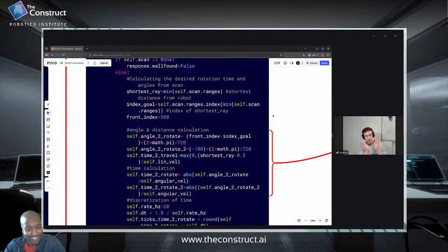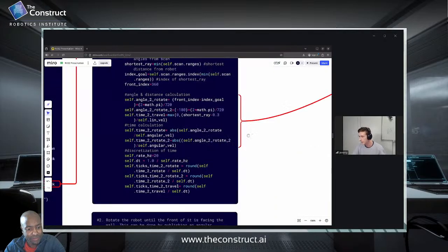I know the angle. The command velocity topic doesn't allow me to define a proper angle. So I had to define a timer for the rover to spin the distance. Since I got the angular velocity, dividing the angle by the angular velocity would give me a certain timer that the action had to run. So let's say I had to turn, per se, 30 degrees. I know I turn 1 degree per second. Well, it's 30 seconds. Yeah. So that's what I actually did, and same logic as before.